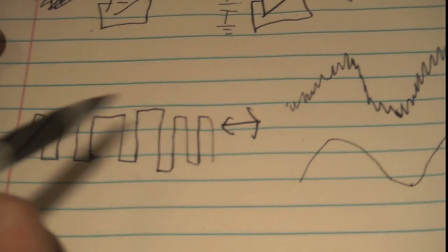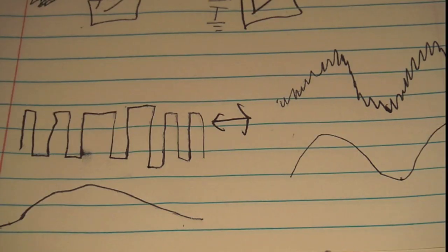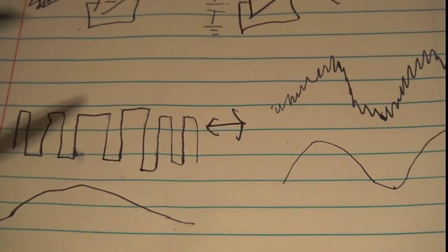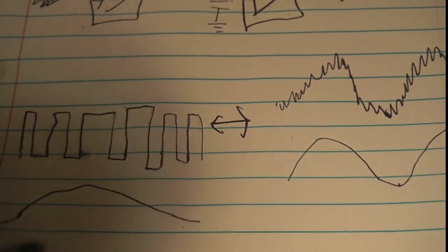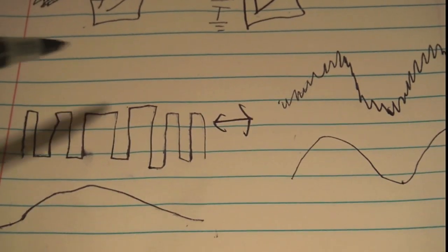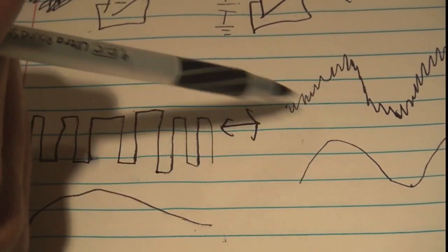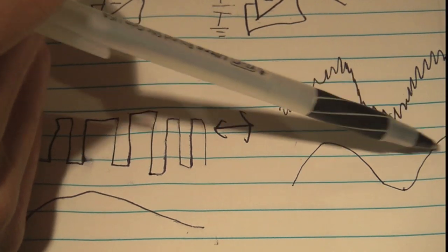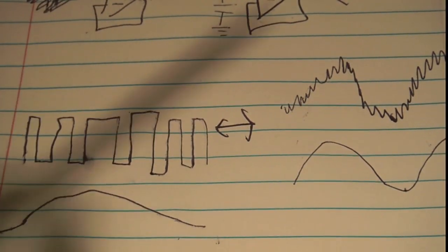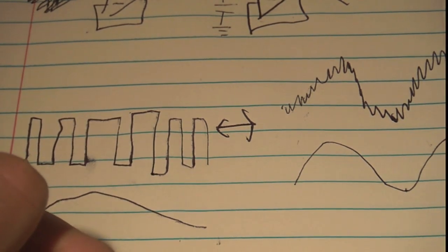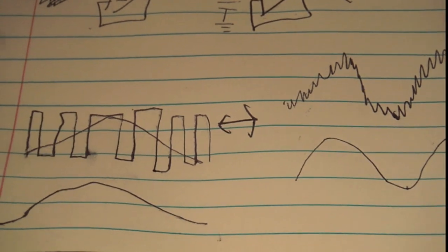So I know you say there's no low frequency here, right? This is just a high-frequency square wave. So we're going to take the average of this PWM value, and so the average is going to be this, okay? So we're passing a low frequency. Now you're saying, where is the low frequency? Well, it's the same thing as this sort of AM modulated signal over here. The low frequency is this wave, and the low frequency is this, because if you notice, the average value goes up and up and up, and then down and down and down. Okay, so that's essentially what a low-pass filter is.